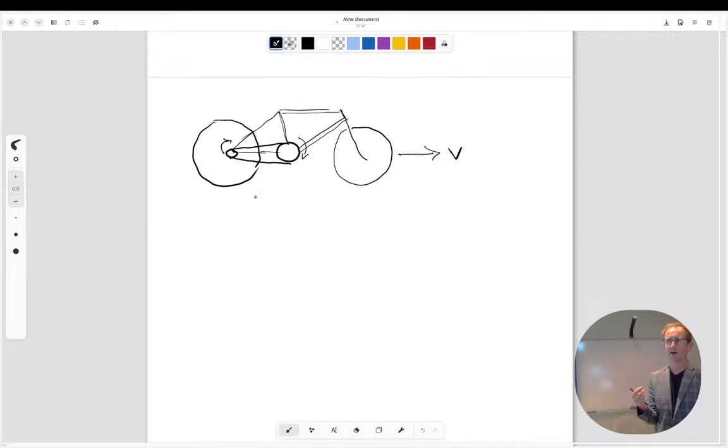Okay. Why does it affect top speed? Because with an object with a smaller gear ratio, the gear can spin much quicker, right? Per one spin of the gear attached to the system. Okay, so if you're pedaling a bike and you want to go fast, what do you want? Large gear ratio or small gear ratio? Small gear ratio.